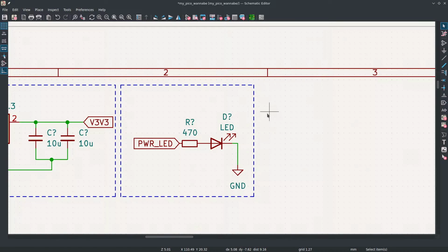So the thing I mentioned earlier with not being able to provide much power out of your microcontroller to power an LED, like even just driving an LED at 10 milliamps, the Arduino can only drive like 3 LEDs at that in ideal situations before you risk damaging the outputs. So I'm going to show you guys how to use a transistor as a switch to control your LEDs.